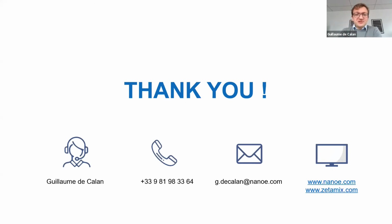So massive part production, how do you see benefits in comparison to casting technology? That's an excellent question. Casting is not going to be replaced anytime soon. And by the way, you can combine casting and additive manufacturing by printing the mold. A lot of people do that, printing ceramic cores, printing molds, printing sand molds. There's a lot of work on that also, and I didn't mention it. I could have mentioned it. It's, let's say, almost an indirect additive manufacturing technology.